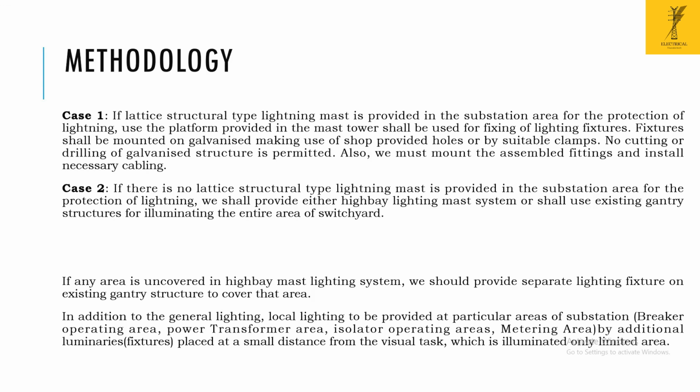It's not recommended because of safety reasons. If you want to change the luminaire, you are going near the live part, so it is not recommended. But in India, in most of the projects we do that as a kind of optimization. Abroad, they won't recommend this because they give importance to safety. If any area is uncovered by the high bay lighting mast, we should provide separate lighting fixtures on the existing gantry to cover that area.